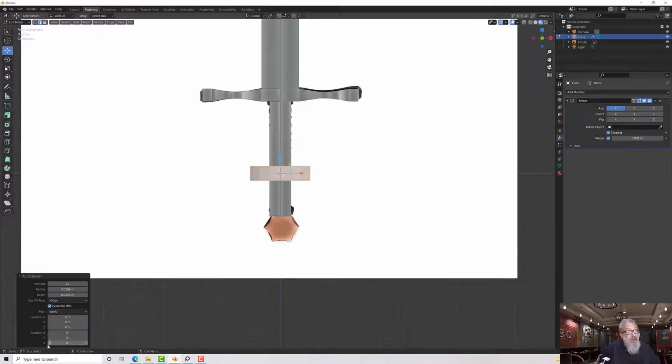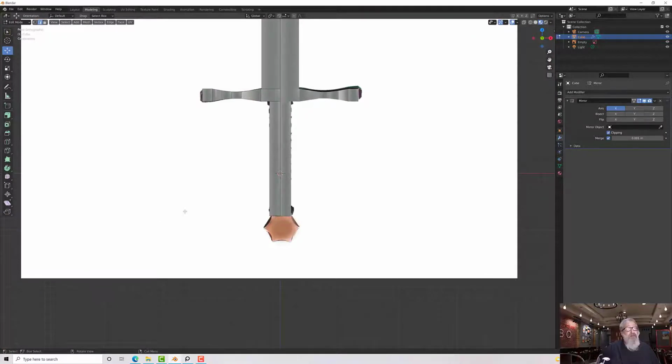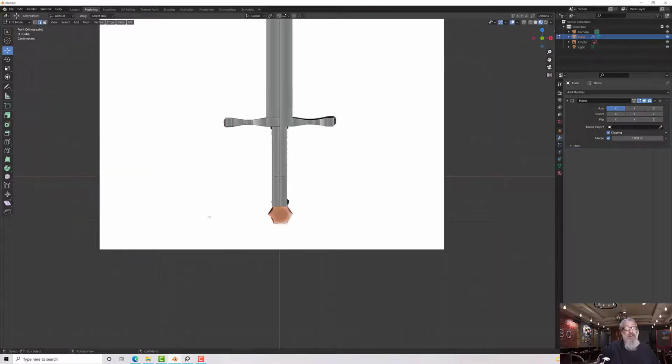Let's set the rotation on X to 90, and then we can start to adjust. It's still too big, so the radius I put 2 inches, let's make it 1.5. Still too big, it's going to be 1, isn't it? So let's type 1 inch in. Whoops, undo. I've completely undone it. Never mind, we can always start that again.